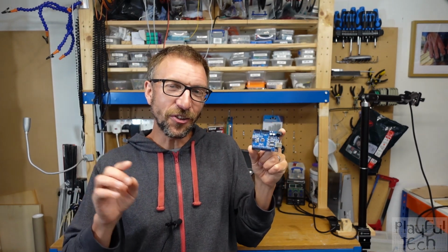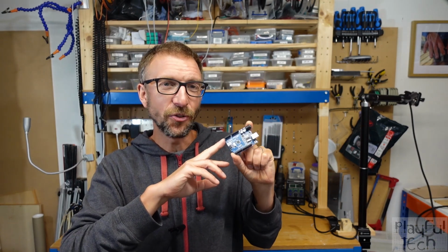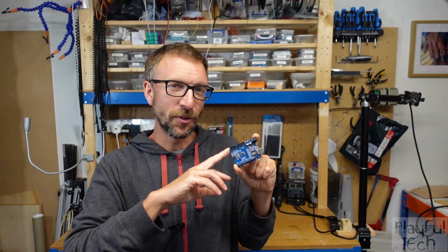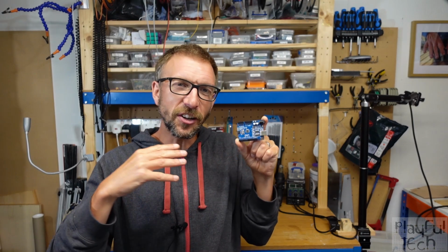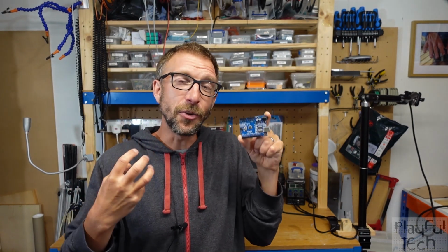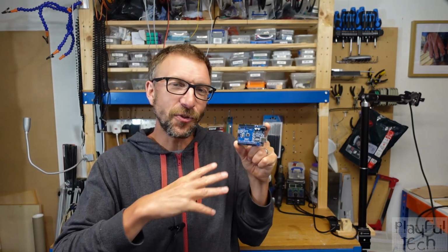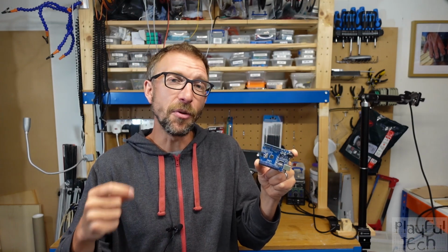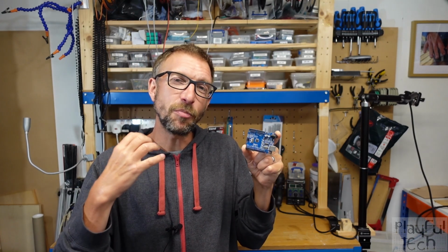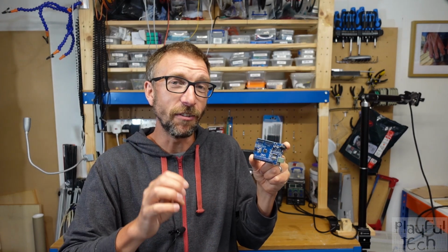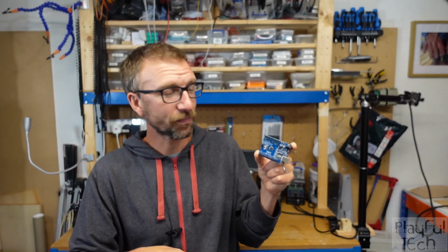However, it's important to notice that we describe these as 5 volt logic level devices. The GPIO pins are not actually designed to provide power to any significant load like a motor. Instead, they're used for transmitting logic signals, highs and lows, that tell the motor to turn. They don't actually provide the power necessarily for it to do so.